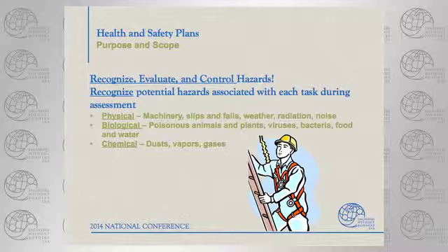Other health and safety issues, you got chemicals, dust, vapors, gases. How many of you plan on using concrete in your projects? Concrete is a corrosive material, and you don't want to inhale the dust, so there's a lot of mitigation steps you can take to make sure that you are protecting your team as well as your community.